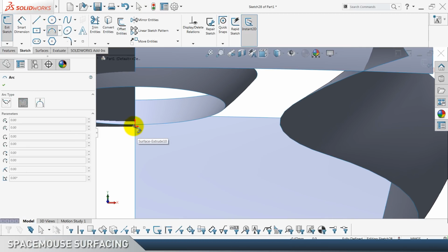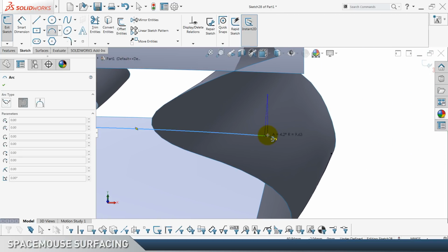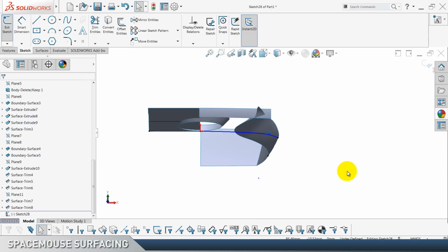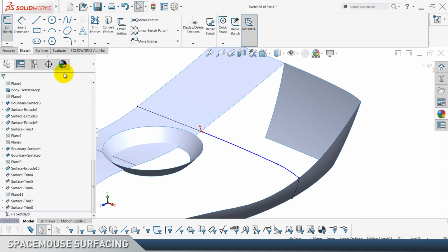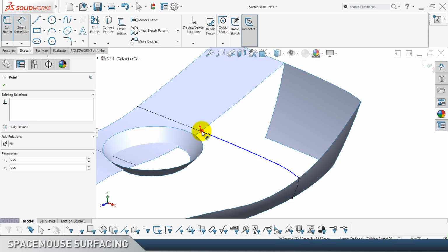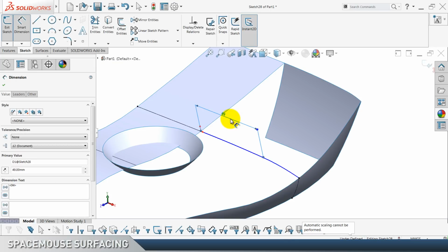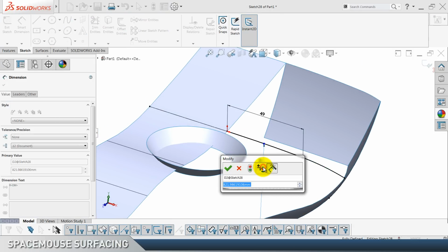So tangent arc goes from the center line we converted all the way right, and another one finishes in this point. Now once we rotate it, this is how it's looking like. So dimension from the point till the point horizontally we have 49, and for this arc a radius of 1250.